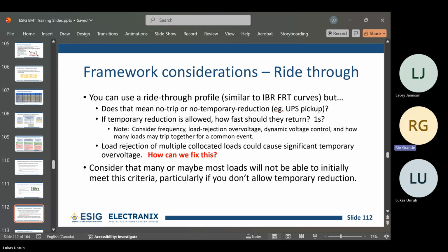Well, that was one of the things, and you can go read the transcript of the NERC technical conference on PRC-029. For those who weren't following it, there was a time where there were really stringent frequency ride-through requirements in PRC-029 that essentially no machines could meet, and basically none of the auxiliary equipment could meet. So part of the justification was I took all of the major disturbances that have happened so far, including the two winter storms, and plotted all of their maximum frequency excursions against the ride-through curves, and they were not even close.